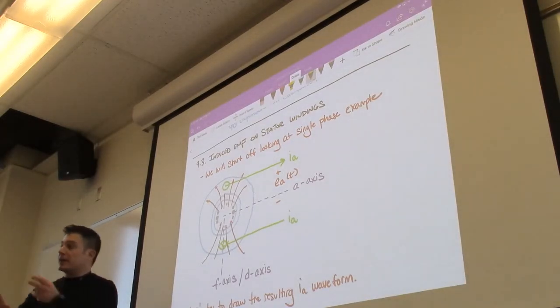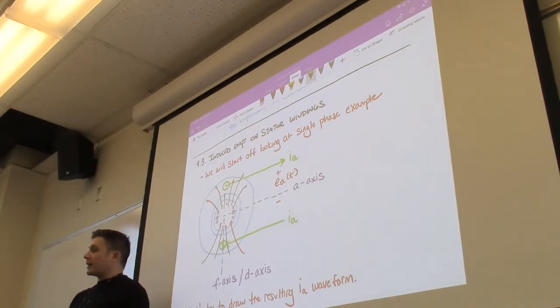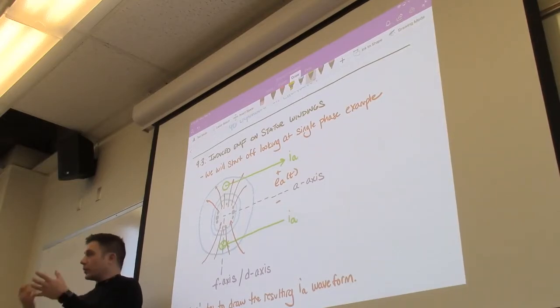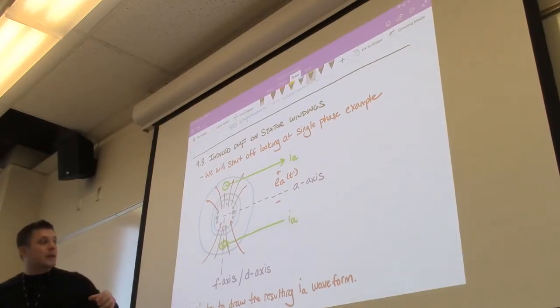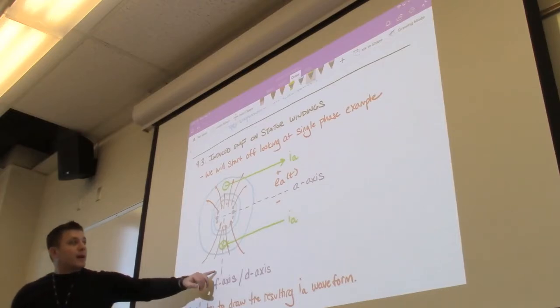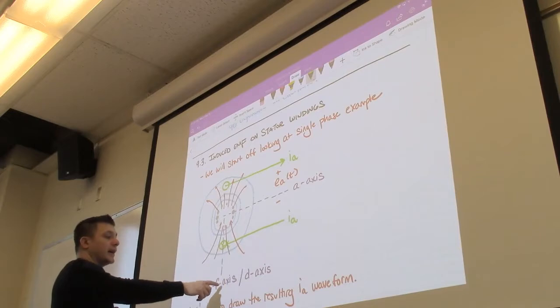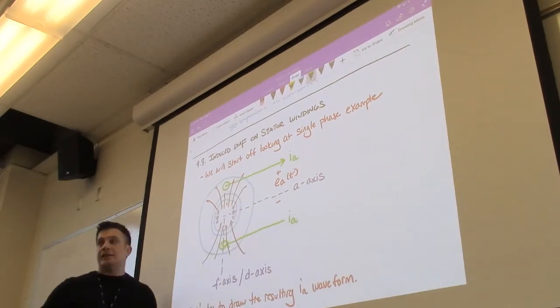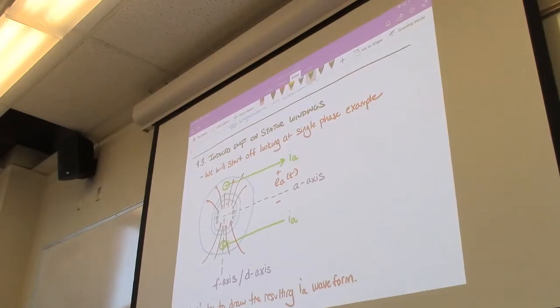The maximum is when they are aligned, right? We saw that example going way back to all the stuff that we did in Chapter 2 related to magnetics, right? It's almost like a pipe. The water goes through the center, and if you want to catch that water or catch that magnetic field, it needs to be lined up. So when this thing rotates by 90 degrees, the coils will line up, and the F axis and the A axis will be aligned with one another. Okay, so that's the point that's right here.